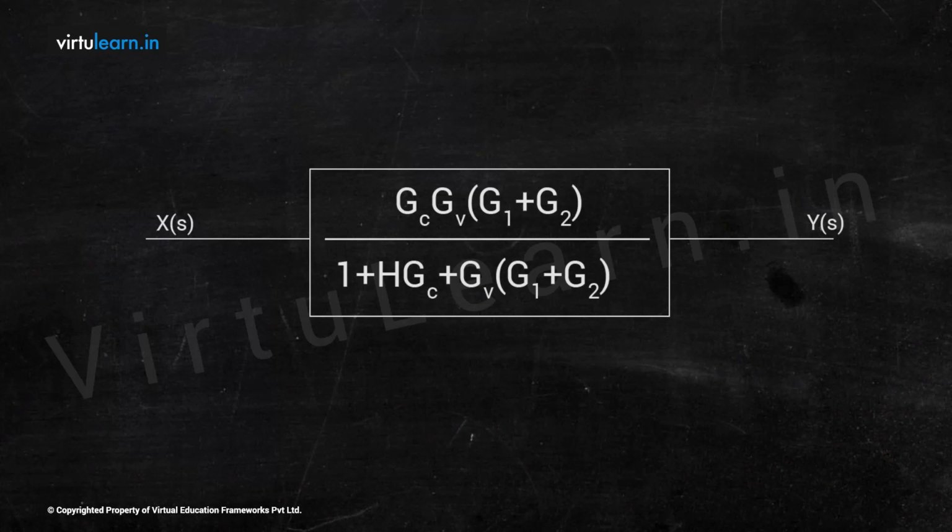If you do that, in the feedback you are getting a big transfer function, that is H1 into 1 plus G3, G4, H2 divided by G3, G4. Now on top of that we have G2, and also we have G3, G4 divided by 1 plus G3, G4, H2. Since these two are in cascade, I can multiply them. Then there is one internal loop here. That loop can be combined and reduced into a single block, and again that can be multiplied with G1. Then again I have another loop, so we can simplify in this way.